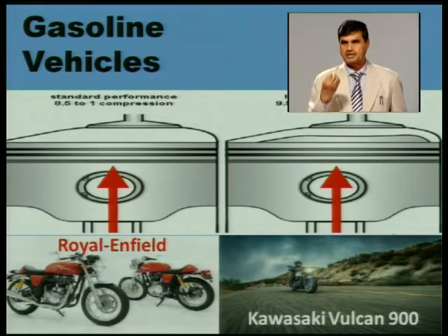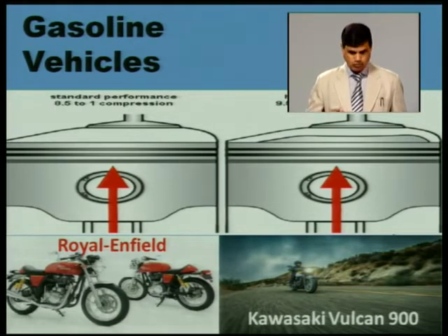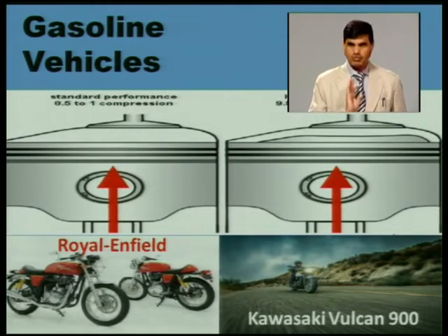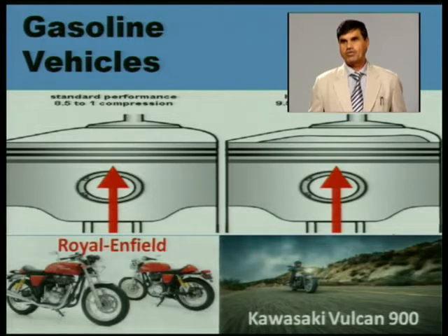But now there are many design changes in spark ignition engines. Even the quality of fuel in terms of octane number is good. A higher octane number means the combustion will be smooth, without any knocking. The compression ratio affects knocking of the fuel. Knocking means auto ignition. When we have a higher compression ratio, the chances of auto ignition of petrol are much more.